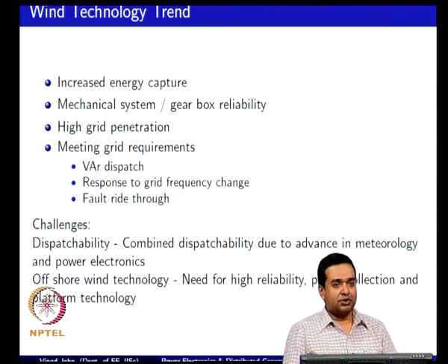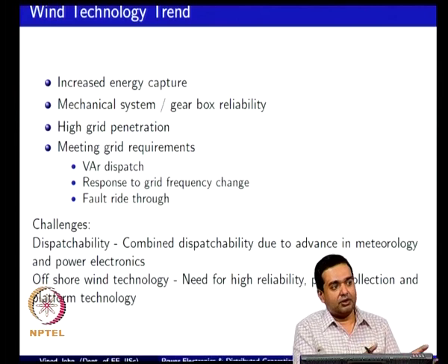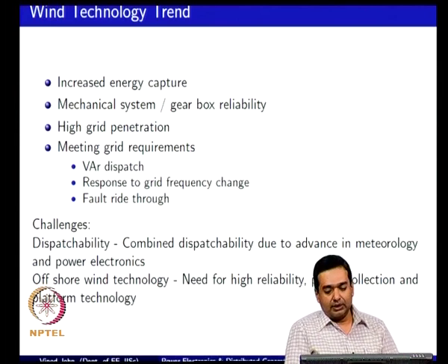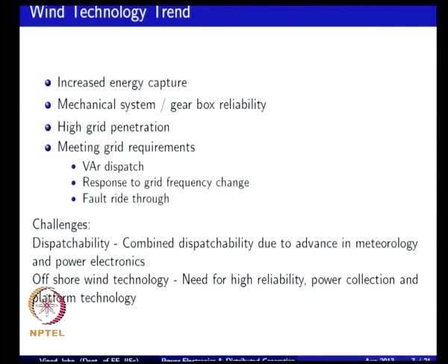And power collection is also an issue at sea. You need to collect the power and transmit it to the land, typically through subsea cables or some form of DC conversion and transmission, etc. There are also mechanical challenges of how to install the turbines in the water. People are looking at the technology from offshore oil and gas platforms and making use of that in offshore wind technology.